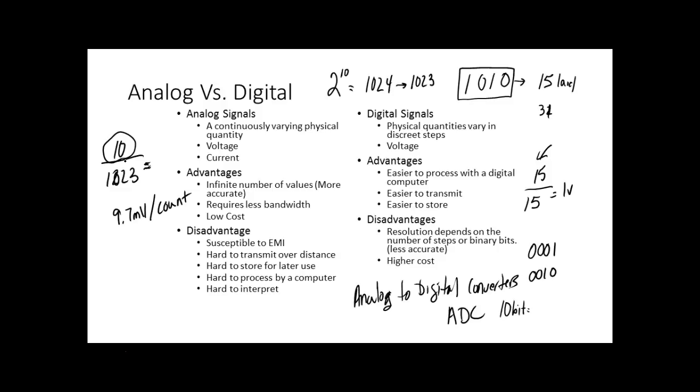That's for the input on the AD. Now, they'll usually accept some things over 10 volts, of course, because it's not going to blow up on you. It's just that if you put over 10 volts in on it, it's not going to give you a true value. And if you put under 9.7 millivolts on there, it's not going to give you a true value because now you're out of the resolution of the A to D converter, right? You understand?